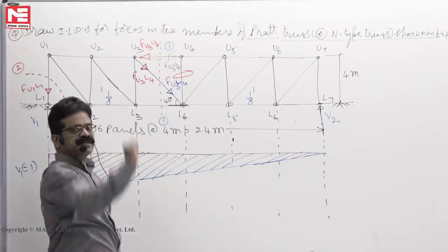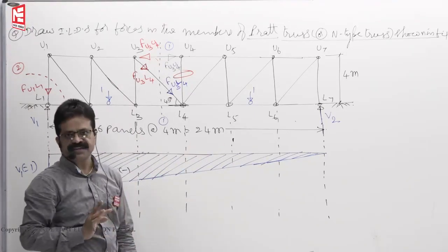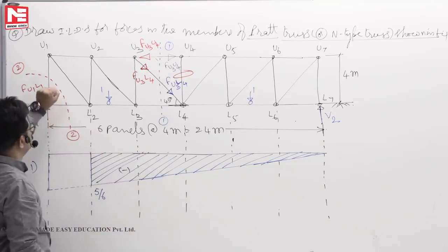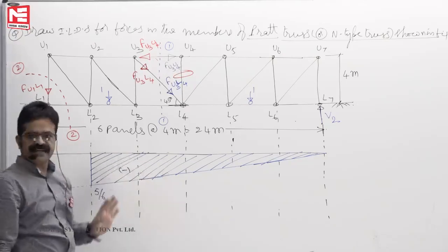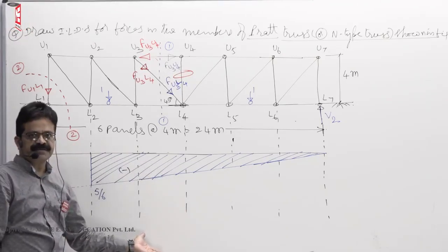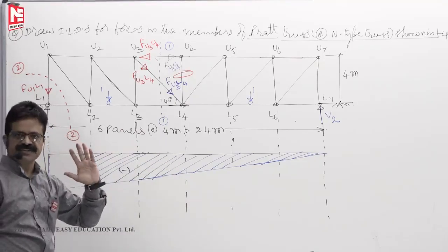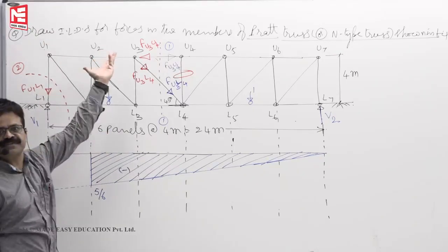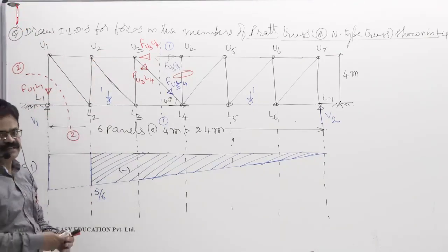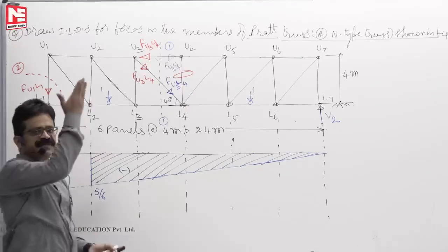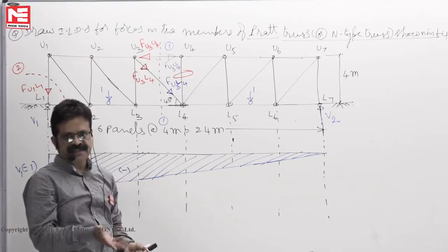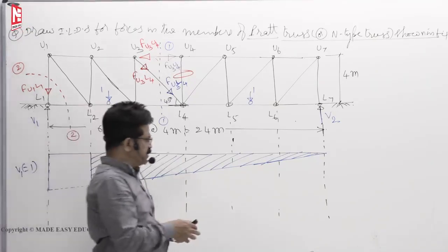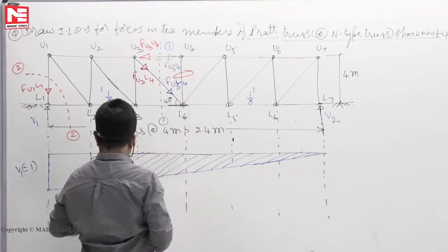To push it up or down depends on whether it is tension or compression. If the force in the member is compression, remove the support, pull it down so that you will get negative, because you want to take compression negative. Supposing that force in the member you get tension, V1 tension, remove the support, hold it, lift it by 1 so that it goes above the reference line. So plus like that. So depending on the sign conventions, you can lift it up or down. Take tension positive, say, so lift it up. Tension itself is negative, so push it down. Our choice. So this part is over.